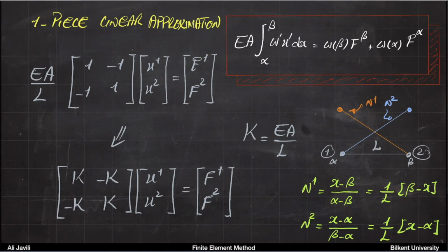Now, it turns out that if you want to go to a two-dimensional finite element method, you need the mathematical description. For one-dimensional finite element method, because you can always think of these elements as springs, you don't really need to connect a differential equation to a spring. For a two-dimensional finite element, there is no spring, all you have is a differential equation. So when we go to two-dimensional FEM, we need to do that. Okay, that's one thing.